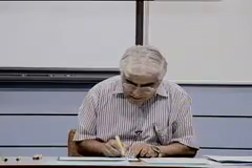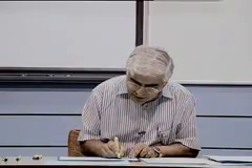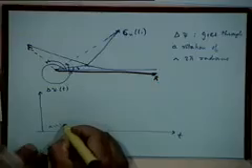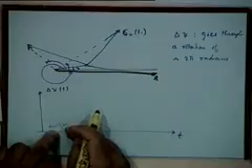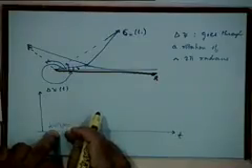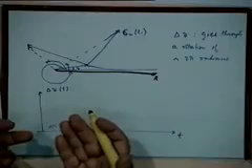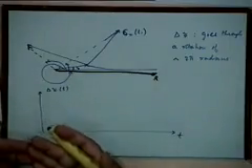So if I were to plot this as a function of time, if you look at the output of your FM phase demodulator, which will be proportional to psi, or psi plus delta psi. Psi is constant, so I am not worried about that, right? Let us look at delta psi as a function of time. Most of the time the noise is small and delta psi is fluctuating around some mean value of psi, right? Suddenly this spike occurs and there is almost a phase rotation by 2 pi radians.